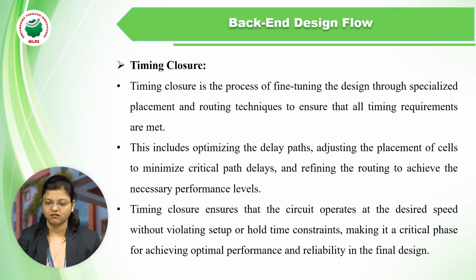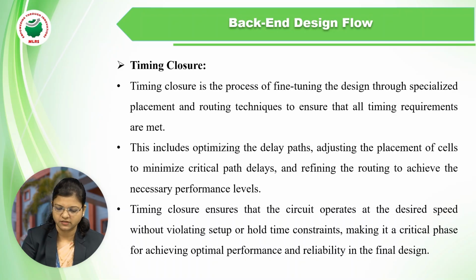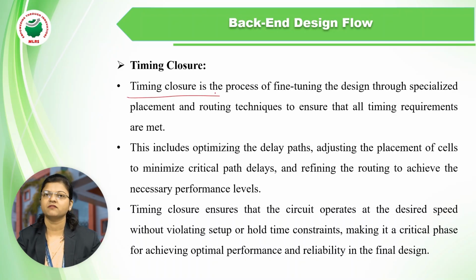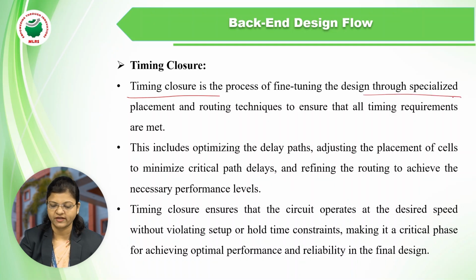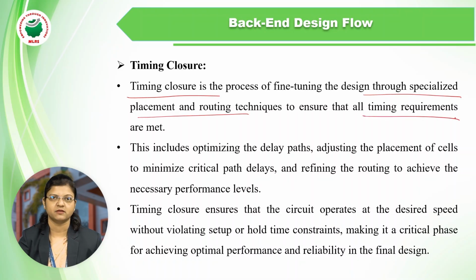Then timing closure is nothing but the process where we have to see whether the timing is correct, or whether the design is fine tuning with each other components, and specialized placement and routing techniques to ensure that timing requirements are met, whatever the specifications we have given. So for those requirements, we have to check whether the timing is proper or not. This will include timing related issues like data delay paths.